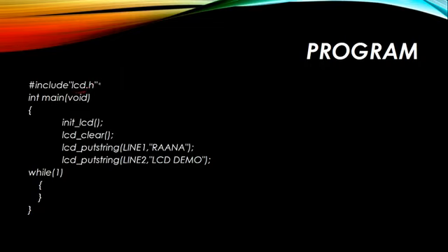This is the main difference between programming the LPC1343 and other types of processors. The programming is quite simple and small when compared to normal embedded C language. So if I just call the header lcd.h, the LPC1343 knows what internal functions are required to perform to display the characters onto the LCD. So lcd.h is the main header file for interfacing the LCD to the LPC1343 ARM processor.